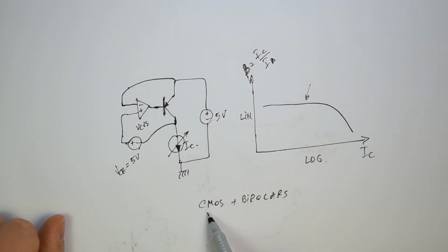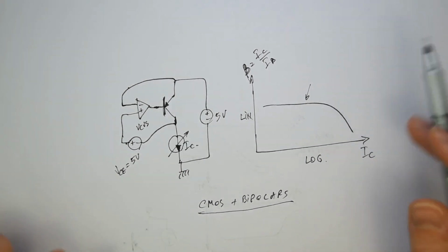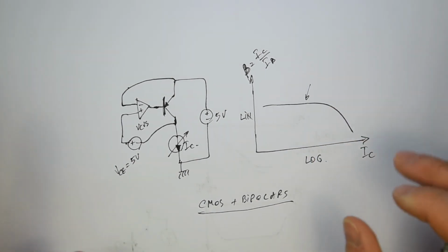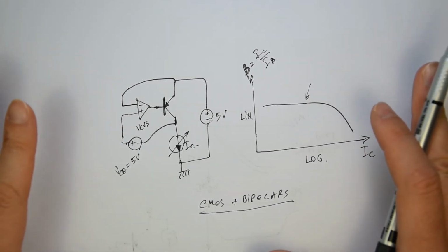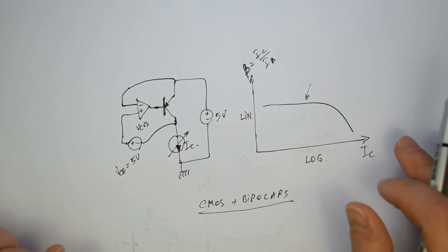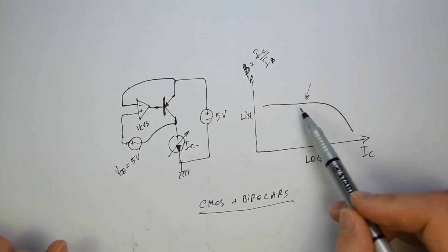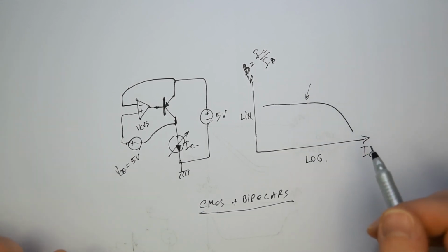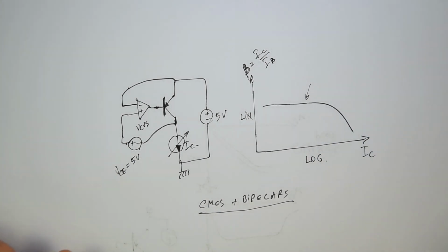And this is useful, especially in the beginning when you learn about the new technology and you are not sure about the characteristic of the transistors, and you want to be sure that you understand the effects and the way the transistor is behaving. Sometimes you have a nonlinearity, sometimes you have a certain drop or a slope that is not as it was in the previous technology. So you have to really check this kind of things.